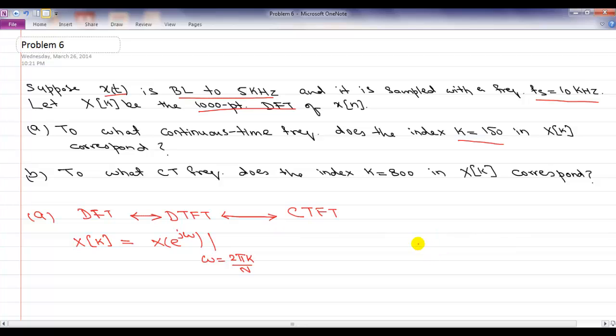So technically DFT samples DTFT from 0 to 2 pi. Right? Remember, X[0] corresponds to little omega equal to 0, and X[N minus 1] will correspond to little omega equal to 2 pi times N minus 1 over N, which is simply 2 pi minus 2 pi over N. So DFT samples DTFT by going beyond pi.